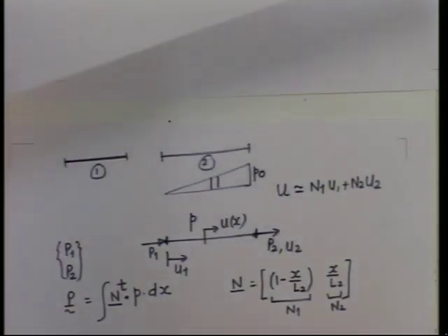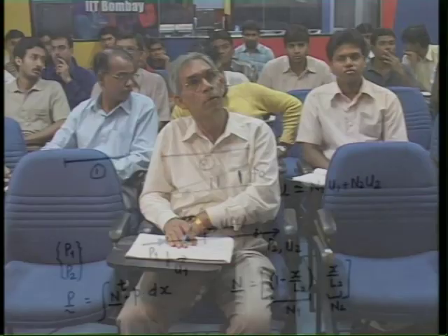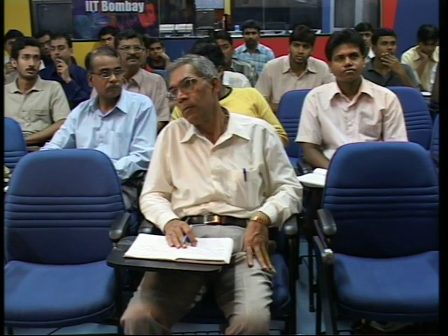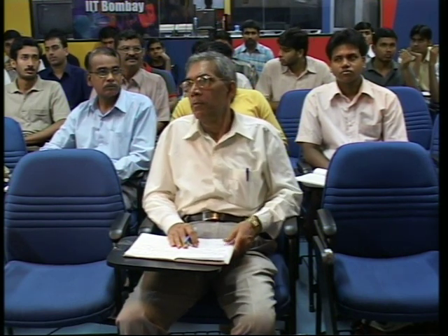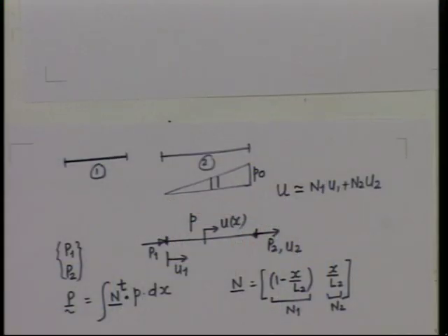Because displacement we don't know and we are just approximating by u hat, it has to be an approximation, but not always. That is why we got the exact solution last time when we solved our problem, between 0 and 1, a boundary value problem, and all the nodal values came out exact. The reason was that the exact solution also was linear, but here it will depend upon the loading.